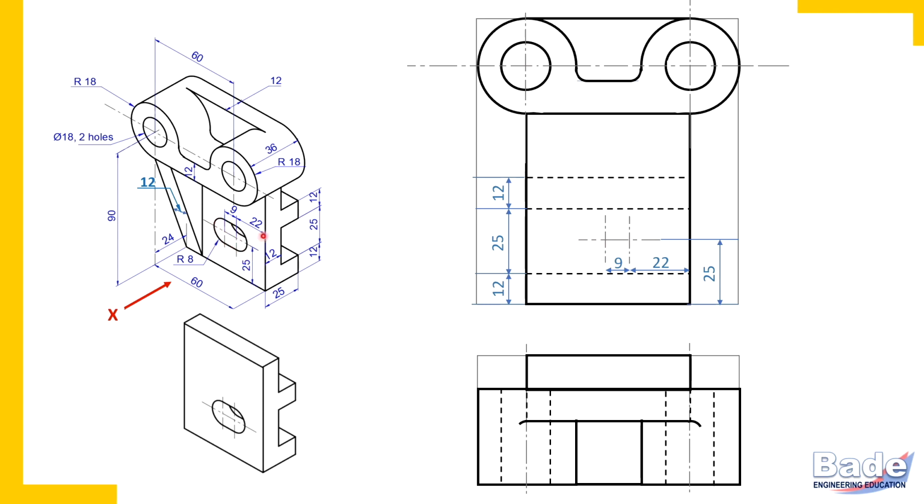So this is how we have drawn those two center lines which we can see here to draw those curved edges, and the radius of each curved edge is 8 mm. So draw those semicircular edges here with radius 8 mm. And then complete the shape by small principal edges here, parallel to length edges. So this whole opening in the front view is complete.